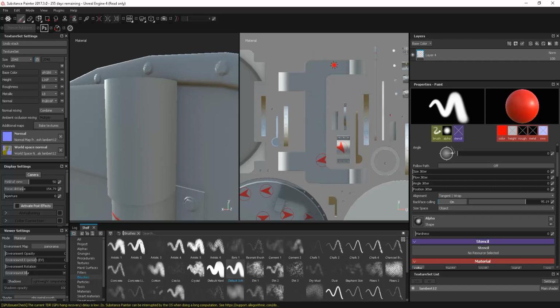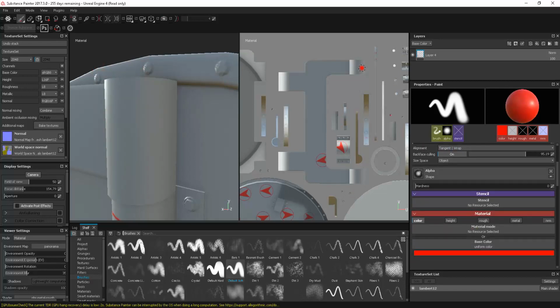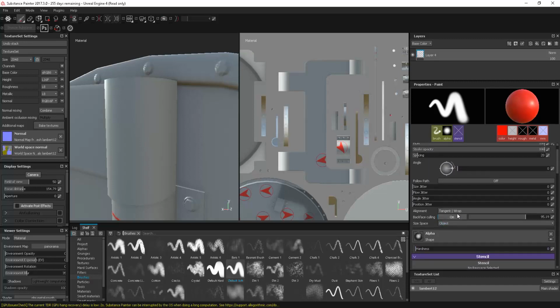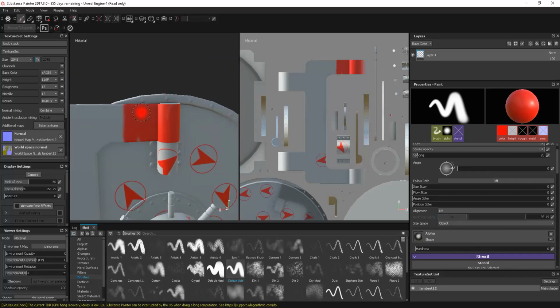So you can see on this, I've got this UV shell separated out for this particular part of our mesh. If I go in here and if I just do it at the minute and paint, then we're still going to be able to paint on the other surface. You can see that going over there. But if I go in and make sure I'm on my brush, change this to UV, what that's going to do is only allow me to paint over that UV island there. So it's not painting on anything else, it's only painting on that. And that can be really handy for painting sections in. Okay. So those are the options for painting in.